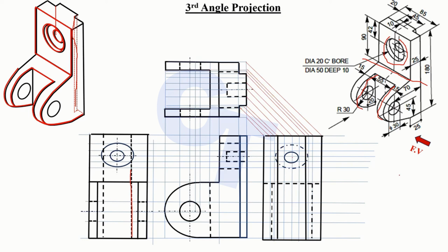And let's draw the other one. So as you can see, I'm also going to show that there's a circle which is hidden detail right here. So let's show it. You can see right there. And now I'm going to draw a center line. Okay, so that's what we have. But on our circle, we don't have center lines, so let's add some center lines right there. So this is going to be our information.